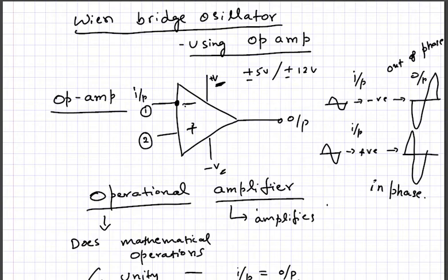So whatever you feed, its opposite sign will come out at the output. So if you feed a DC voltage of say -2 volts, the output will be amplified. So note the size of these waveforms. That is why I made them bigger. So it is amplified.